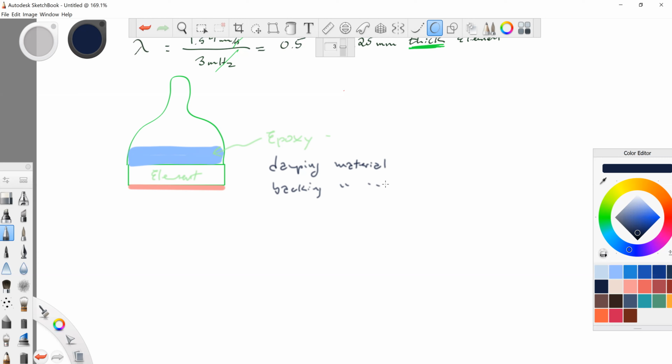I didn't mention this when we went through this. Commonly made of epoxy resin impregnated with tungsten filaments. When the electrical spike excites the PZT, the backing material restricts the extent of the PZT deformation. And so, by the way, that causes the quality, or the Q factor, quality goes down. If we could hear it, it would be an ugly, ugly sound.